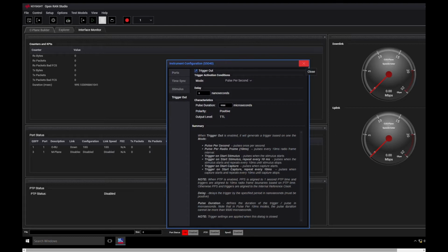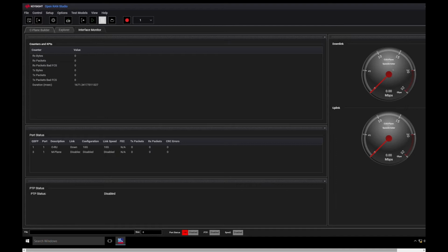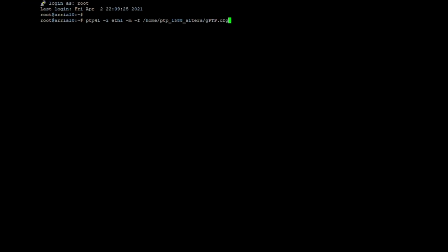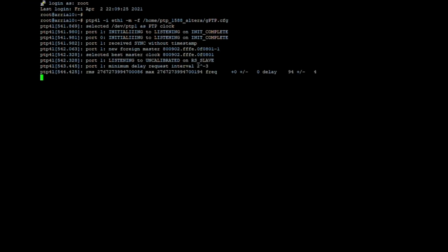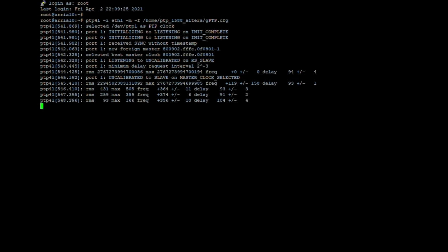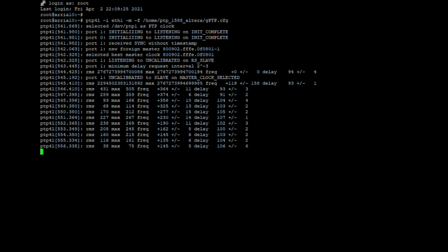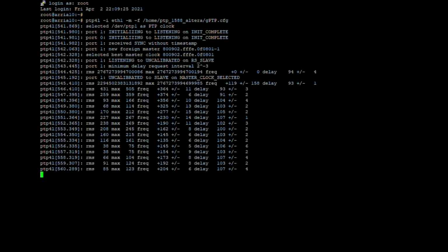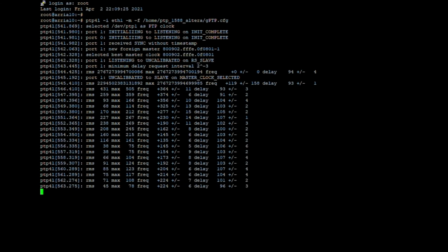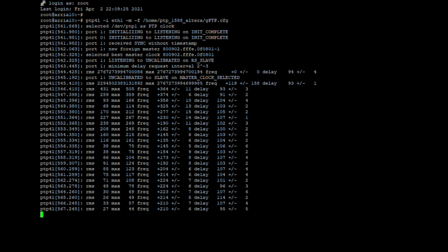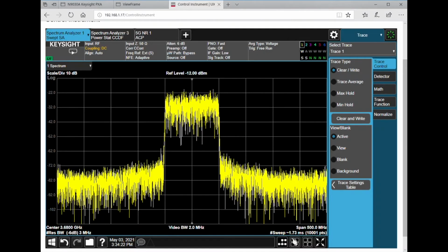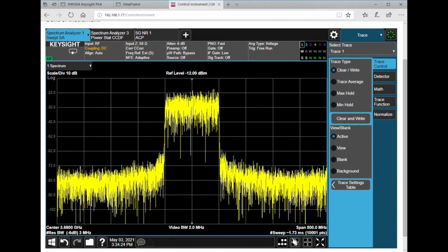signals. In this demo, we test out our front haul S-plane messages by turning on IEEE 1588 v2 PTP. We've set the O-DU as PTP master, and our O-RU will receive PTP packets and process them in the timestamp unit to maintain proper synchronization. Once timing and synchronization is achieved, we can transmit over the user plane.